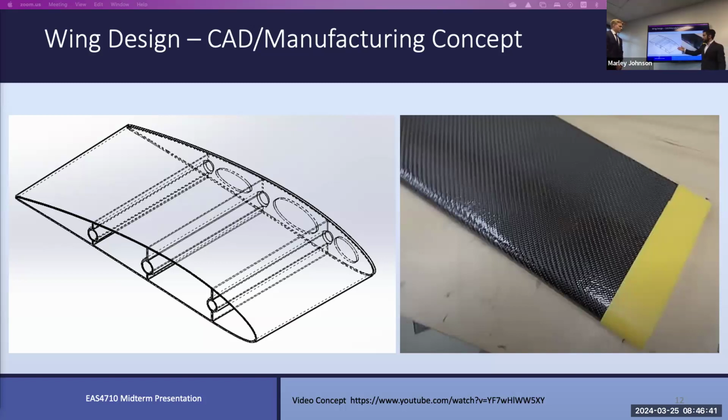Here is a cross section of one of the wing segments. You can see in the view here, we have 3 printed spars going along the entire length of the wing. 2 of these will be used to house the carbon fiber rods, such as the ones that we have there. And the middle one will be used to run our wiring. We have also optimized the rib at the base of each segment and are working on strengthening the end section.